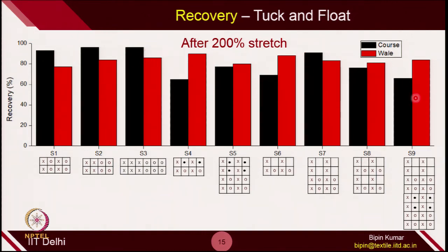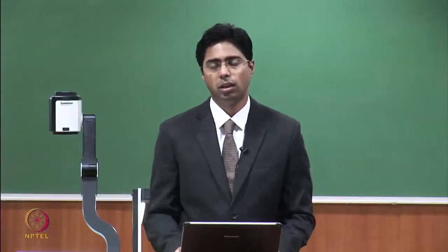For the other stitches, the variation will be like this. So, it depends again what type of fabric design you are making. You can selectively make your design of experiment, either you can vary the rib type, or you can vary the tuck alternatively and float, and you can do this simple study to observe the fabric behavior.